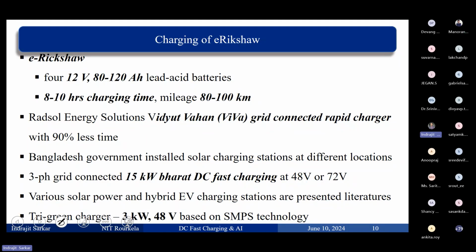That is one thing. Another thing is, when it is an e-rickshaw, since there is extensive use of battery, and those batteries are lead acid batteries in the current state of the art, the battery lasts for 8 to 14 months, and the amount of money they have to spend in one year is 40,000. So the battery is deteriorating very soon.